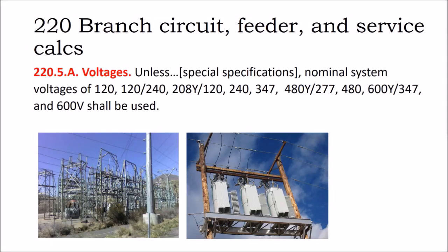So then we get into some other system voltages, and it says, unless otherwise specified, under a special circumstance, nominal voltages of 120 volts, 120/240, 208Y, 240 volts, 347 volts, 480Y, 480 delta, 600 volts, standard voltages for standard electric services should be used.